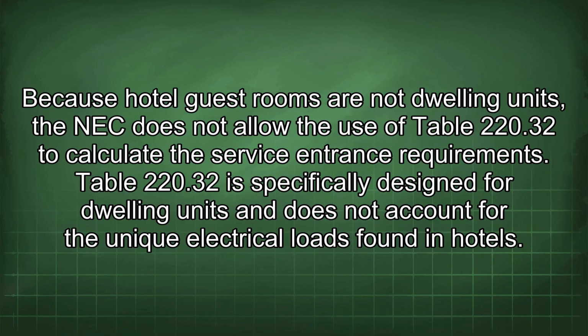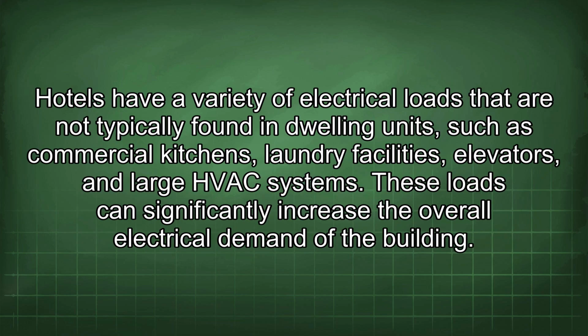Because hotel guest rooms are not dwelling units, the NEC does not allow the use of Table 220.32 to calculate the service entrance requirements. Table 220.32 is specifically designed for dwelling units and does not account for the unique electrical loads found in hotels. Hotels have a variety of electrical loads that are not typically found in dwelling units, such as commercial kitchens, laundry facilities, elevators, and large HVAC systems. These loads can significantly increase the overall electrical demand of the building.